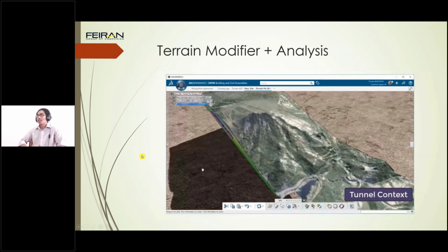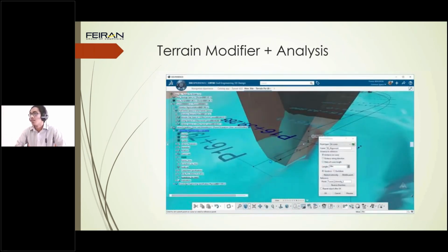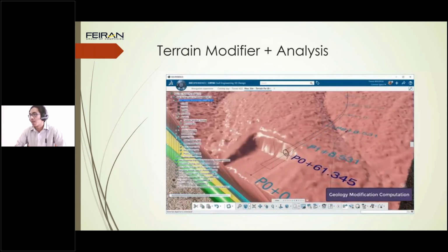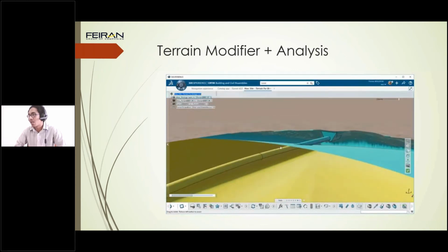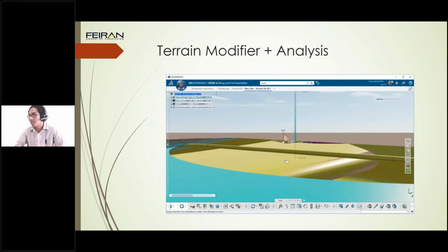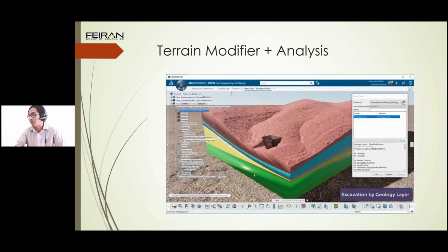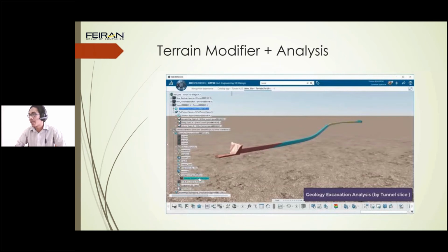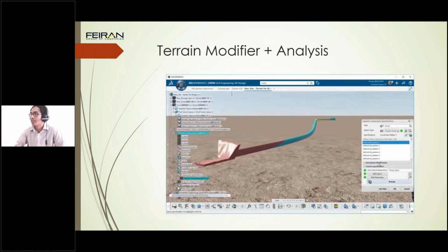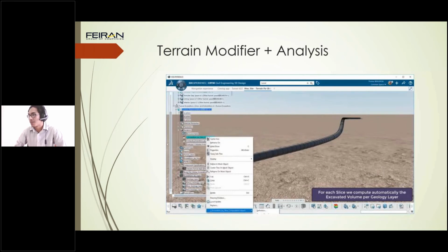Okay, this is focusing on a tunnel area of the smart topography analysis we performed earlier. By this capability, we can actually study the geographical data or bedrock data that we have, because for a more dense bedrock, it involves a lot of drilling. It will incur a lot more cost compared to a less dense bedrock layer. So by this analysis, we can actually see how many volumes there are for a particular bedrock layer.